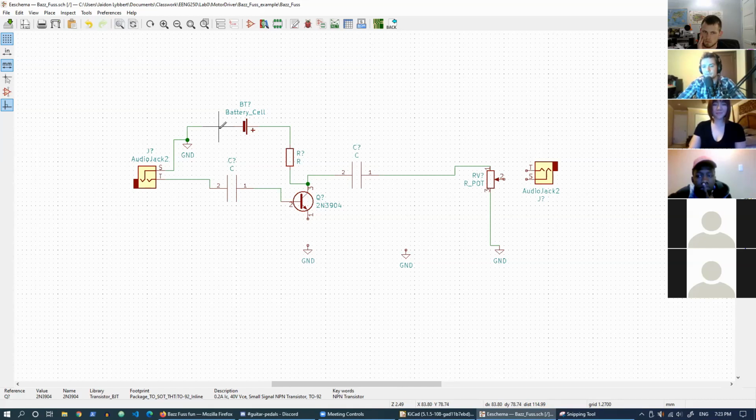Well, that's what it does if you put that external ring, like the red block on the audio jack. If you attach the ground to that, it turns it into a switching jack, so that when you plug your guitar in, it starts using the battery. Oh, I see. Gotcha. Okay, yeah, I think I've heard of that, but I don't really know exactly how that works. But that makes sense actually. So yeah, that could be a design consideration when we actually get this thing printed. That's a good point. I'm glad you brought that up. I forgot that was a thing, but I faintly remember reading about it somewhere.